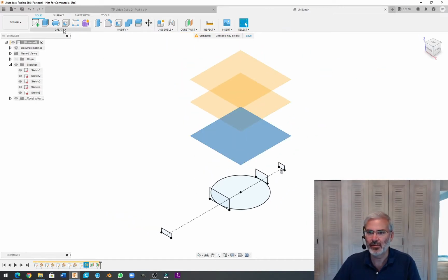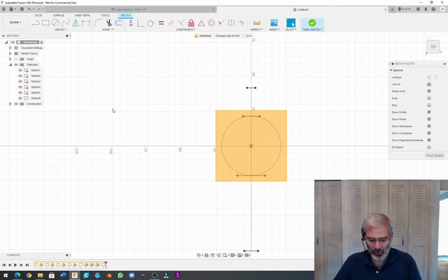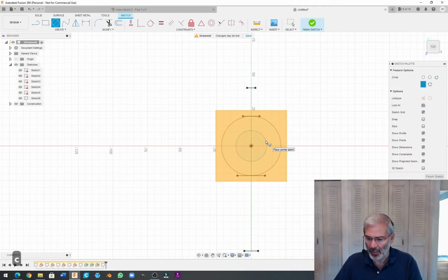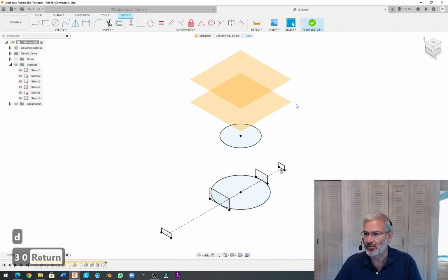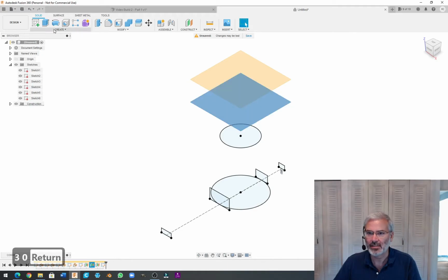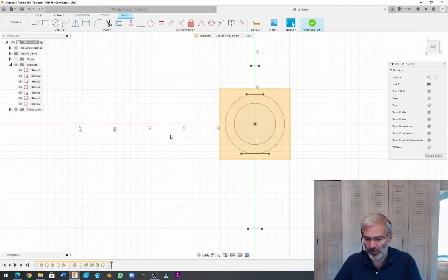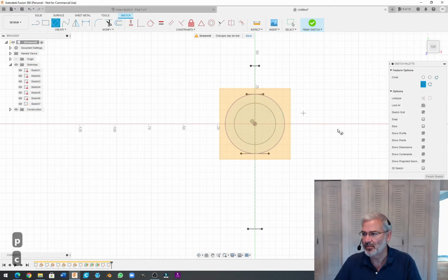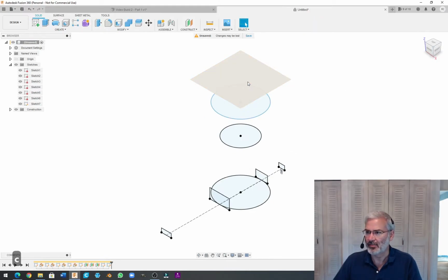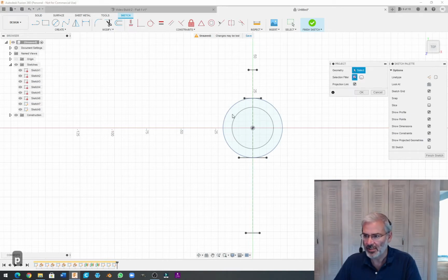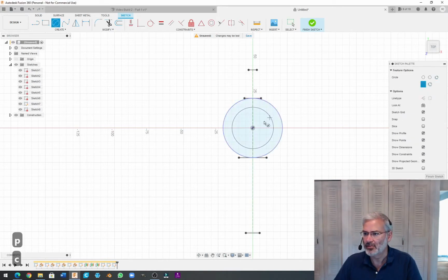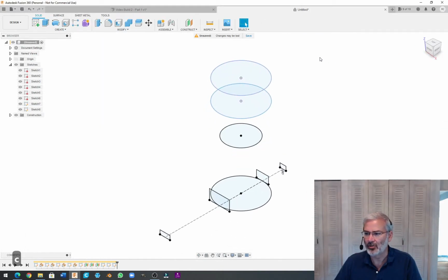We'll start this one, create sketch. We'll use the circle key and then the dimension key and make that 30 millimeters. The next two will be the same as the bottom circle. We'll click the sketch. We'll project onto this outer circle. Use the circle key to snap to the previous circle and do the last sketch, which will be the exact same thing. Create a sketch. We'll project onto the outer ring. Use the circle command to snap, finish sketch, and look at our model.